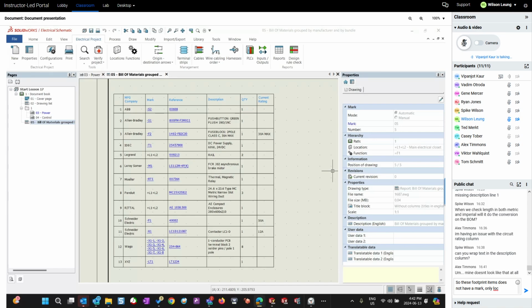Don't break into many tables, give me one table. Click apply and update your report. So you would have one big table. Close this, right click on the BOM report, update button. Thank you, sir. So you've got one big table now. So later on in the next step, we'll break it into multiple tables, picking one property, one variable, one factor.